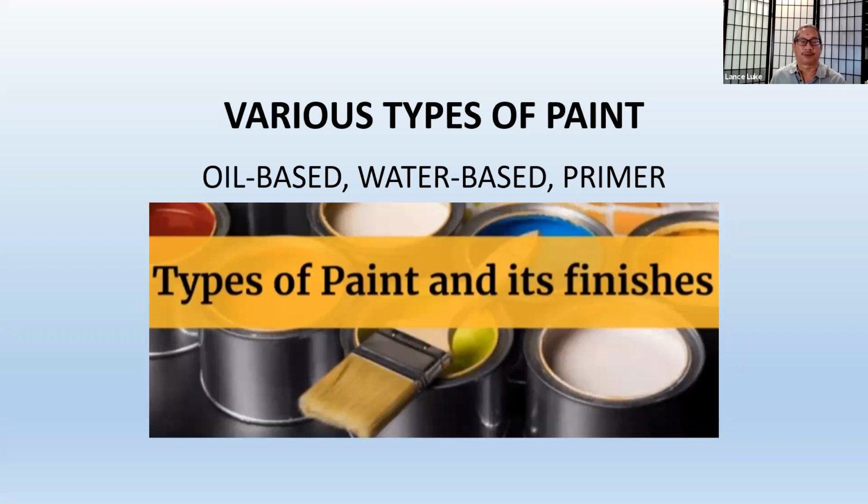Okay, and I've seen that before, where the paint just goes right on whatever surface and it's not clean, and the paint actually adheres to the surface. But it doesn't work in all cases, because if you have a building that has all this soot from the freeway or a smokestack and you don't clean it, eventually the paint's not going to stick.